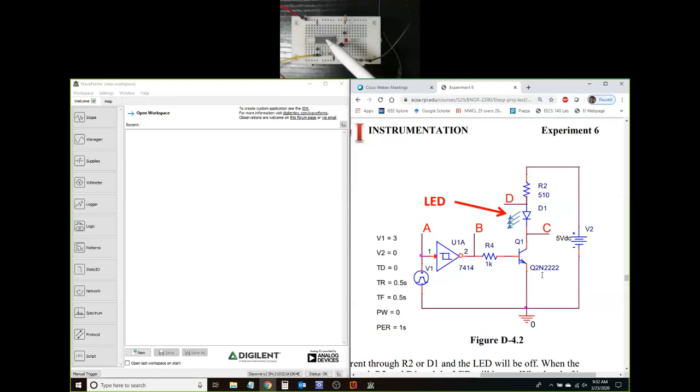Alright, I hope that locks up the autofocus. So pin 1 is the input, pin 2 is the output of that, the first Schmitt trigger inverter. I've used the notch on this IC to indicate that that is pin 1 all the way down to pin 7 and then 8 all the way up to 14. So in a counterclockwise fashion, it goes 1 through 14.